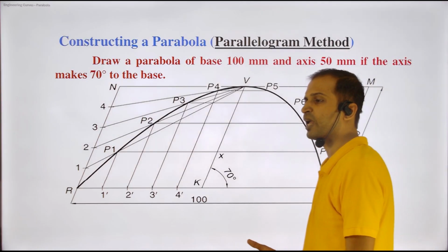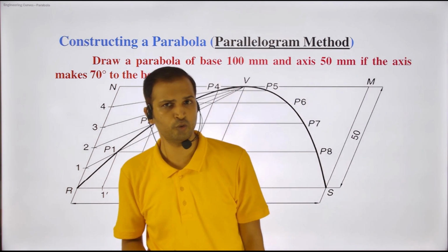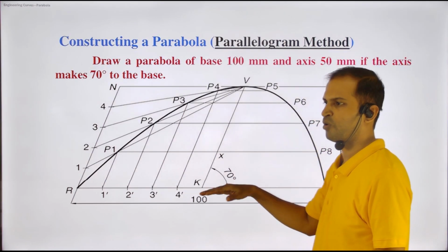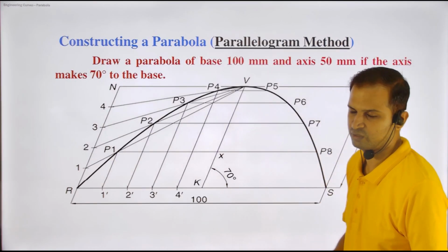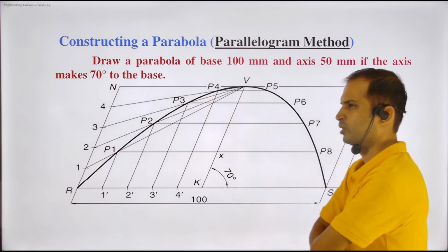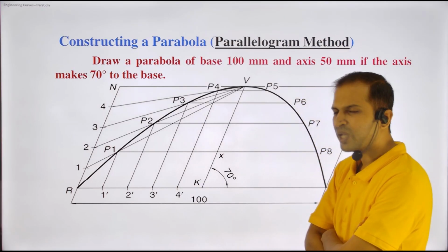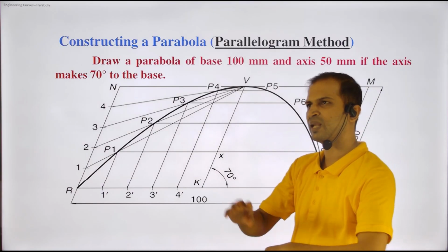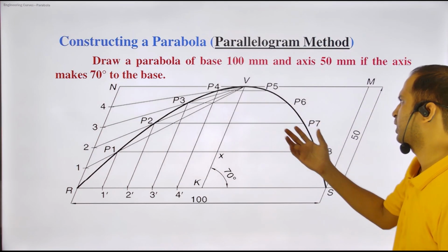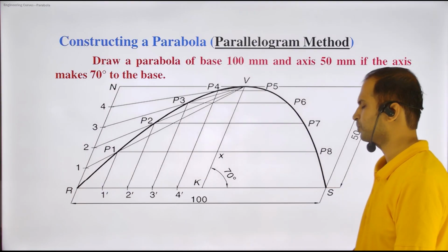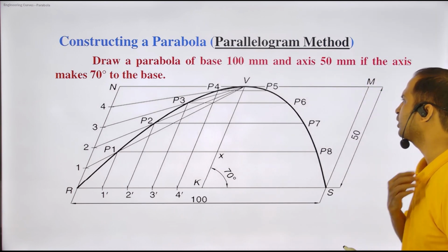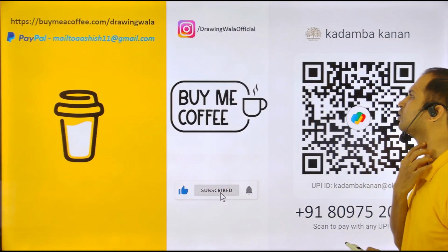The drafter is very important. It makes your diagram very easy and it becomes very fast for you to draw it. If you are not able to use a drafter, you better use a roller scale, but I say prefer the drafter wherever it's possible. A roller scale gives you error. You can draw with a roller scale also, but it takes more time because you have to align the roller scale every time, right? That's the reason I prefer to use a drafter for this kind of drawing. Okay, this is very similar, so we won't go into details. Already self-explanatory. Let us go to the next question.